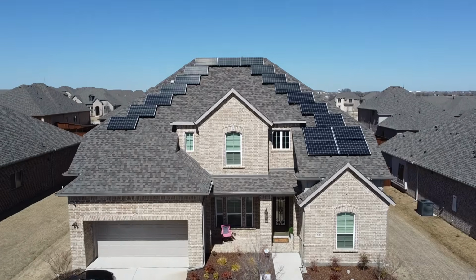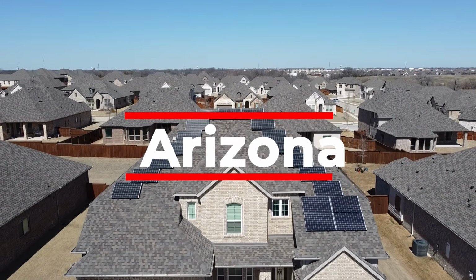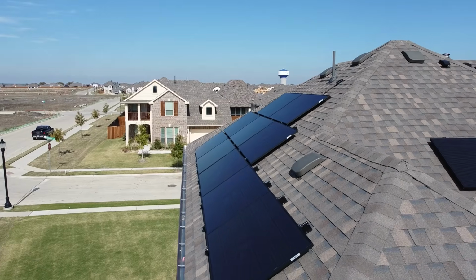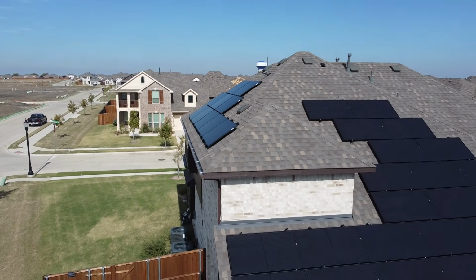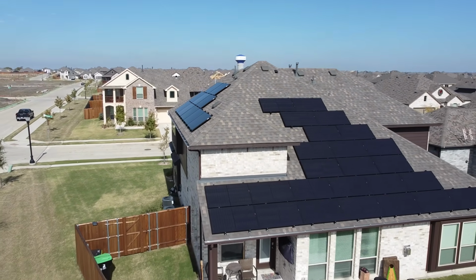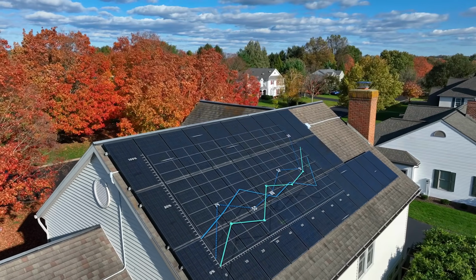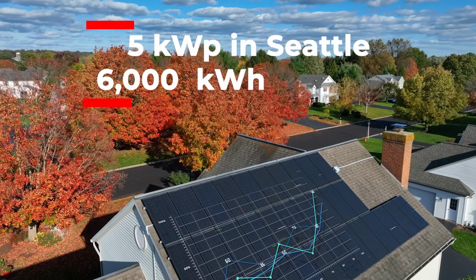Location matters as well. The same 5 kilowatt system will produce more kilowatt hours in sunny Arizona than in a rainy Seattle. And don't forget about panel orientation and tilt angle. South-facing panels at an optimal tilt angle for your latitude will produce the most energy possible. Now let me give you a practical example from right here in Texas. A 5 kilowatt system in the DFW area might generate about 7,500 kilowatt hours annually, but the same system in a more cloudy region might only produce 6,000 kilowatt hours.